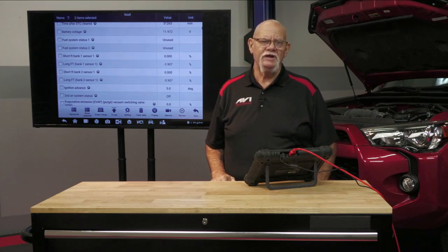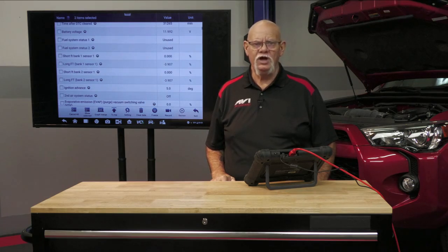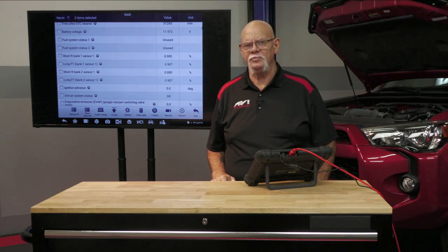yourself. You don't have the luxury of looking at fuel trims at one engine load or mode of operation. You need to look at it at idle, part throttle, cruise, and just before wide open throttle power enrichment, and get an idea where the fuel trims are at, because that's going to help you diagnose the fuel delivery problem.